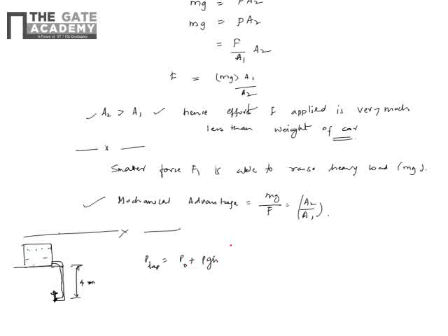the vertical distance between the tap and the water tank. So when it is 4 meters in height, which is the usual distance, P naught is basically your atmospheric pressure, the house atmospheric pressure, plus rho g times 4 meters, where rho you can take as the density of the water. So this equation has a lot of applications. The pressure varies with the vertical distance, and that has a lot of applications.